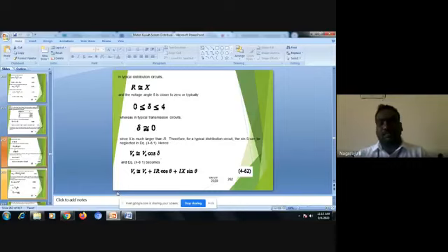Vs, I have, when the delta value is going to 0, only cos delta you will have. Sin delta will become 0. That's why I am neglecting that component. Vs approximately is equal to Vs cos delta plus j into Vs sin delta. That sin delta goes to 0. Okay, so because of that, and since X is much larger than R, for a typical distribution circuit the sine value may be neglected. Vs approximately equal to Vs bar is equal to Vs into cos delta.